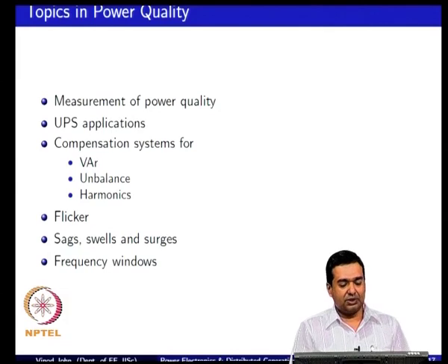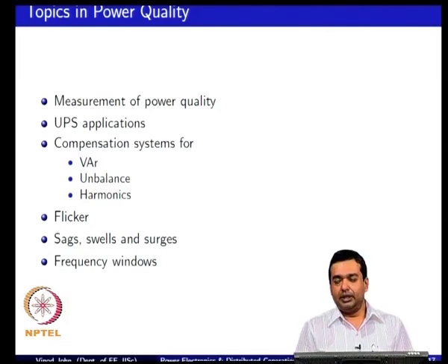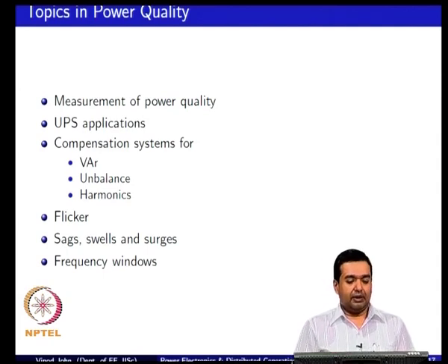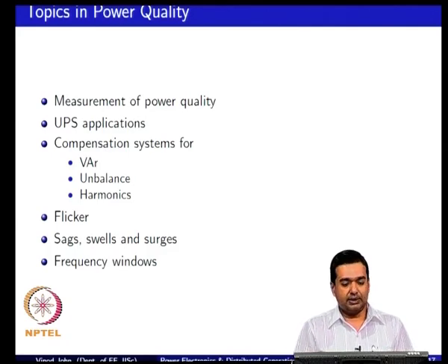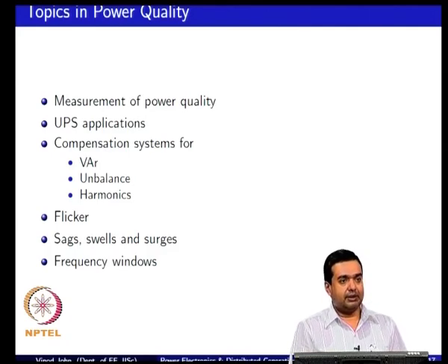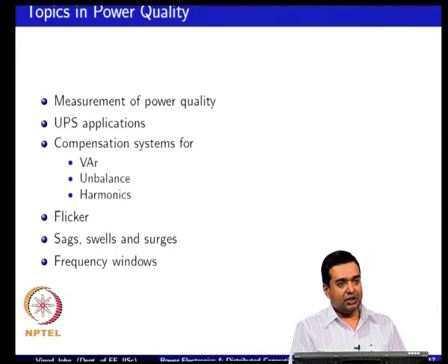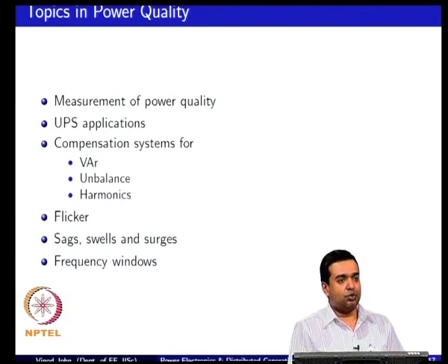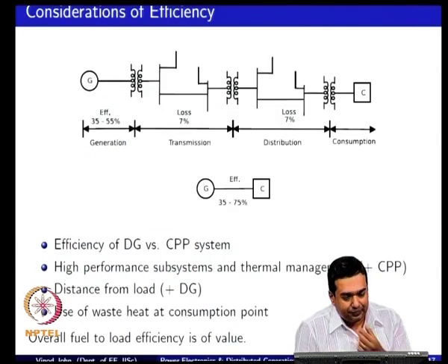You also have issues like flicker, which comes up when you have periodic power injection into a node. You have to deal with sags, swells, and surges in a real grid, and you also have to look at what the ranges of frequencies are that you would need to operate in, and how to operate within that particular range appropriately.